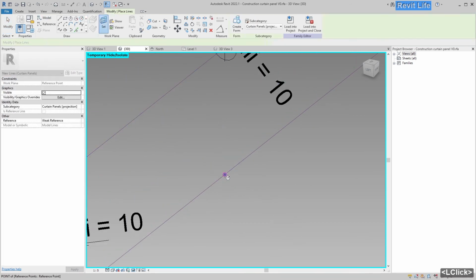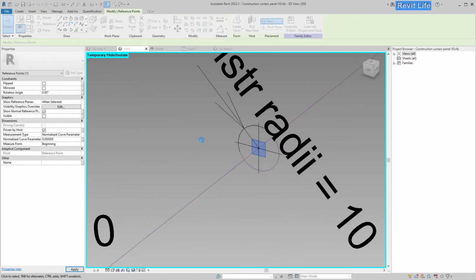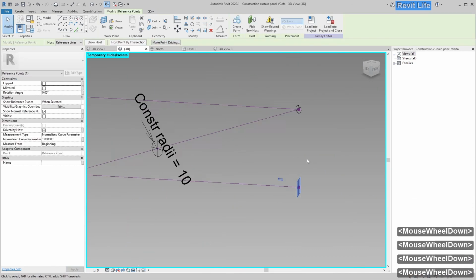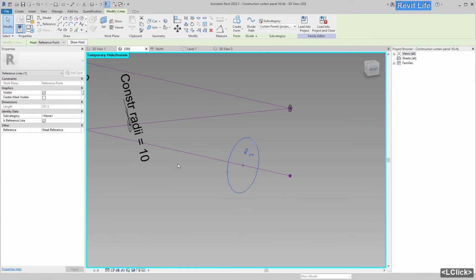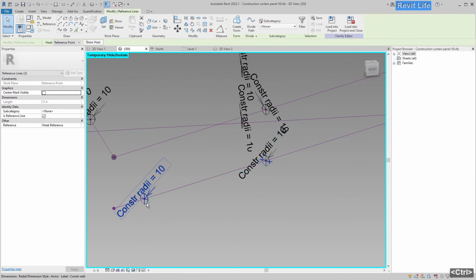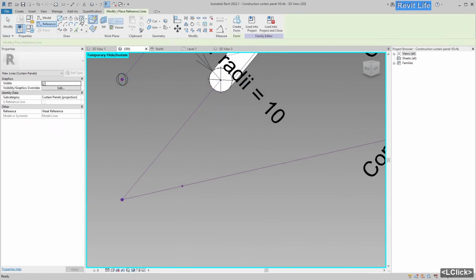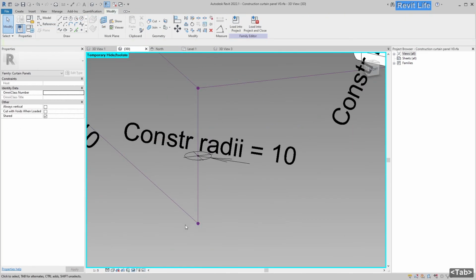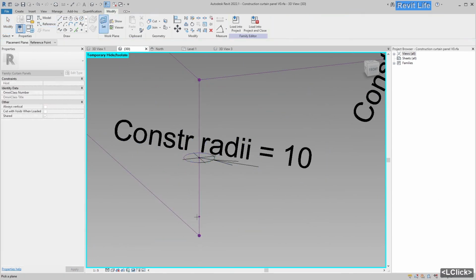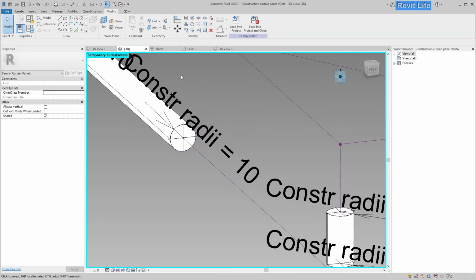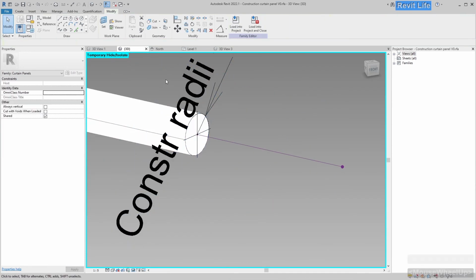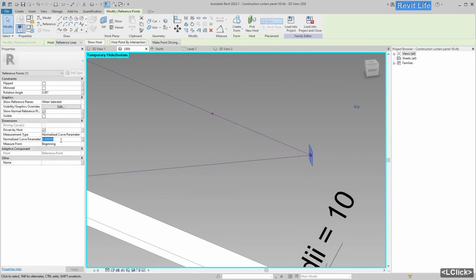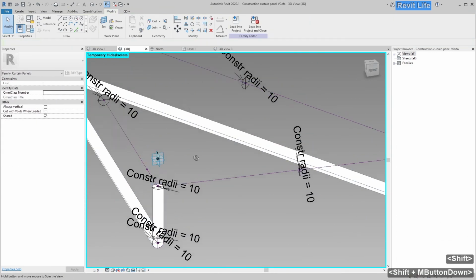And that is the problem that I talked about previously, because the form from the detail lines acts, in my opinion, kind of differently than the form that is created from reference lines. And here I'm trying to mitigate that problem by adding two profiles to this pipe. One in the end and one in the beginning of this lead line. It kind of works, but it's difficult to snap those profiles to the beginning and to the end of this model line.